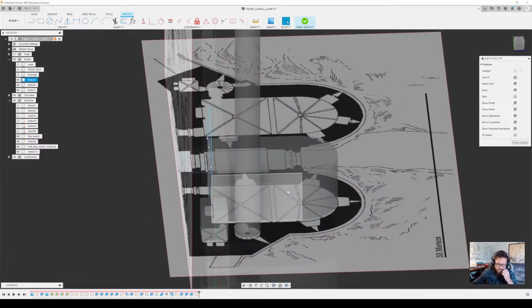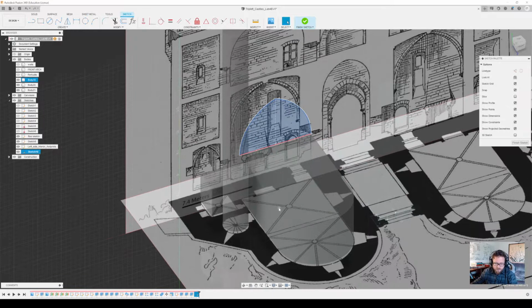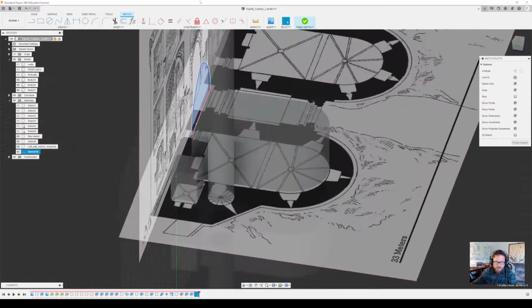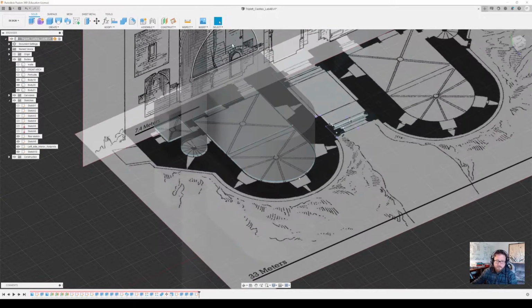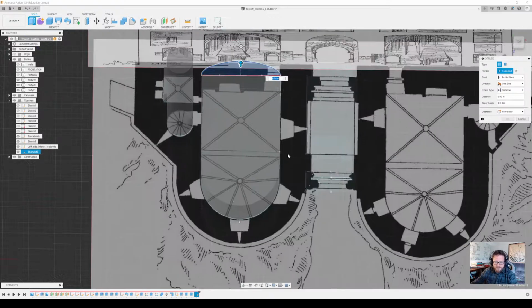We're also going to have to create another piece in here to do the opposite side. So remembering that it's a cross vault, let's just extrude this one first. So the first thing I want to do is pull this out here with the extrude tool, once we finish our sketch, of course. Sorry about that. I'm going to pull this out with the extrude tool, and I'm going to pull it out till it hits this point here.